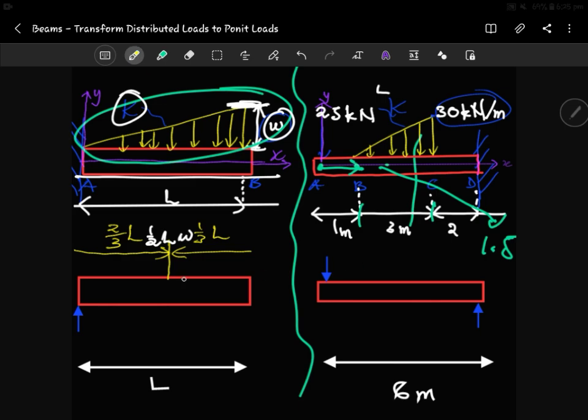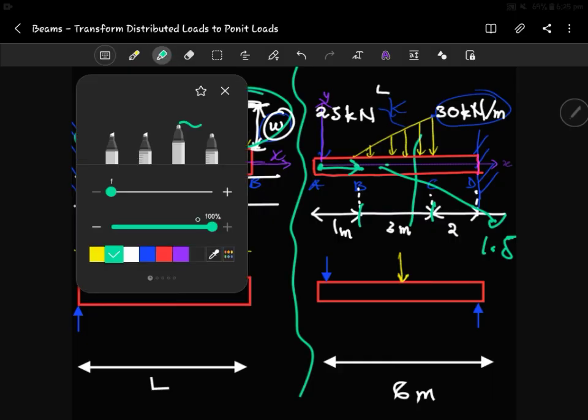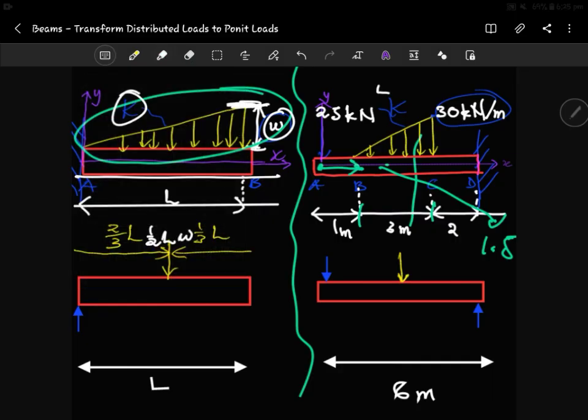If we put the force here, the point load that we are transforming to here, the distance will be, so yeah, now this one. I'm talking about the other one. So the point load from about here to here, which is where the coordinate system starts, will be what we've established. That will be this 1.5 plus this one here, which will be 2.5 meters, right?